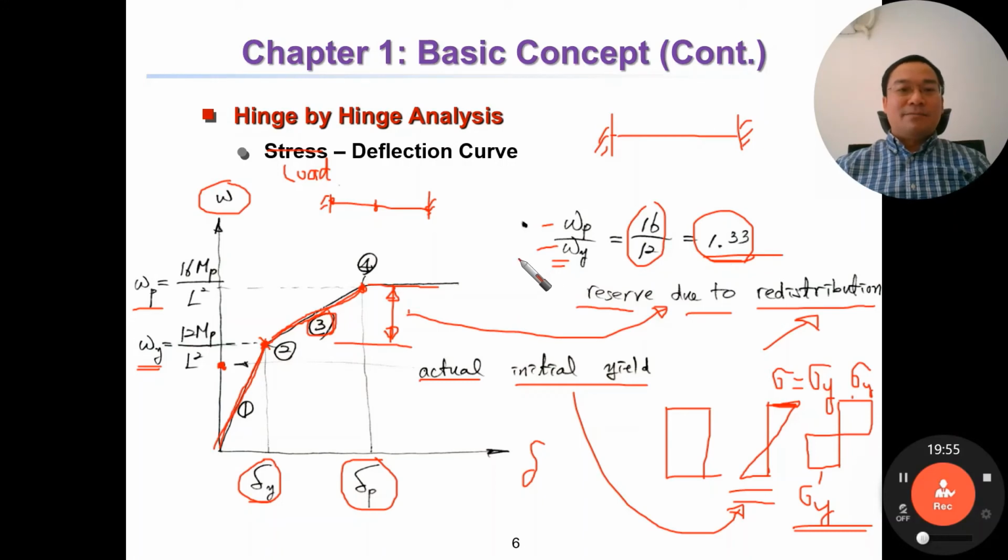Step by step, you can consider the load and the plastic hinge occurrence procedure, and you can calculate the elastic limit load and the plastic collapse load.